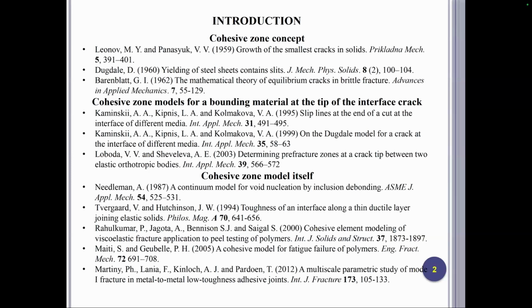This model is part of a modern cohesive zone model, which was first introduced by Needleman and further developed in the following works. We use the simple brittle criterion of the mesoscale type to generalize this model for the adhesive joints between two dissimilar materials.